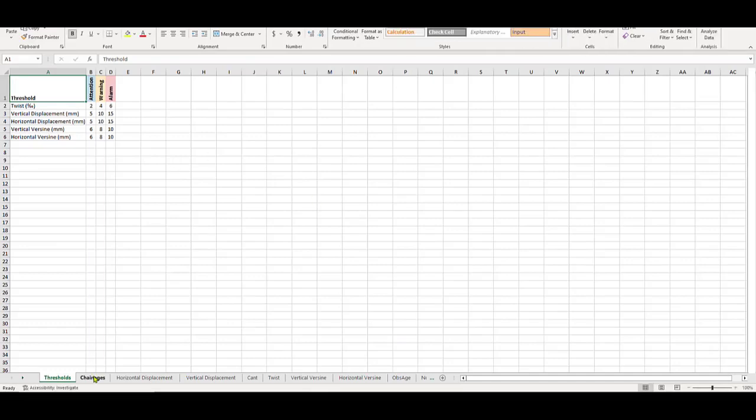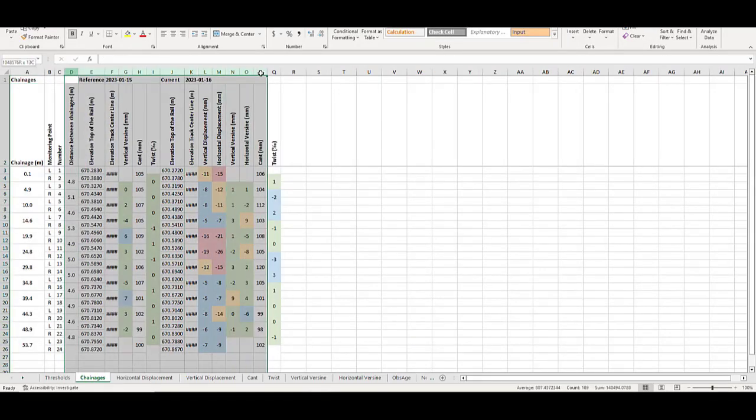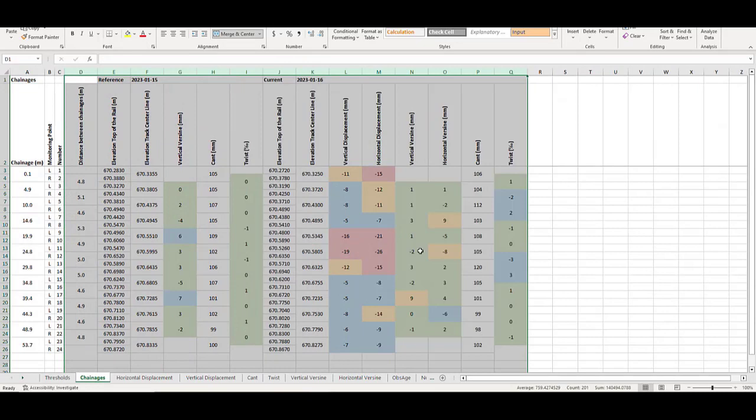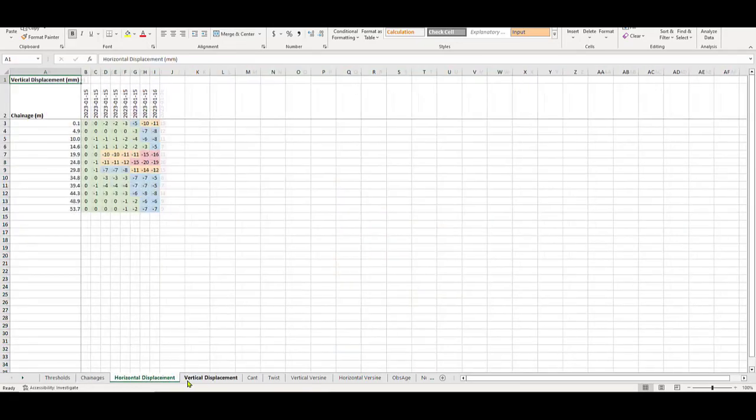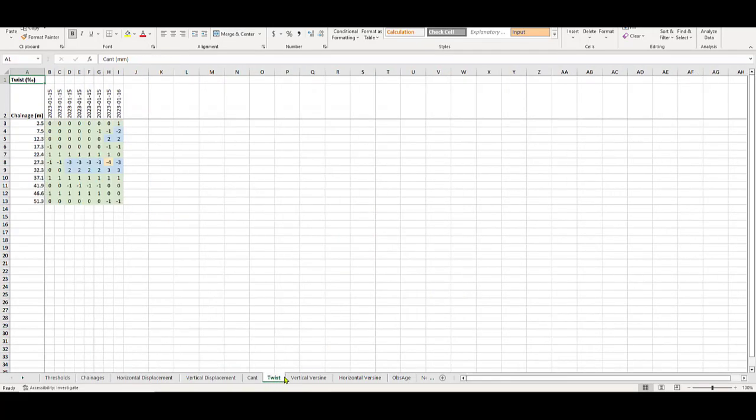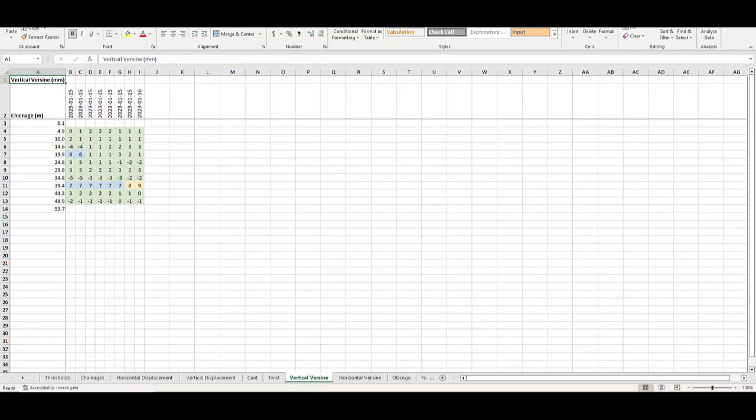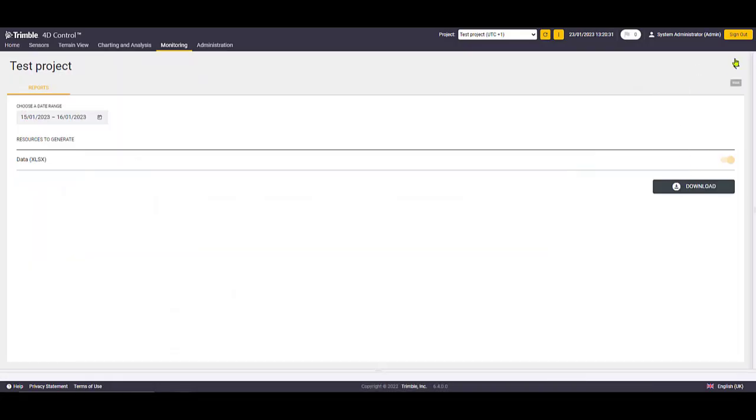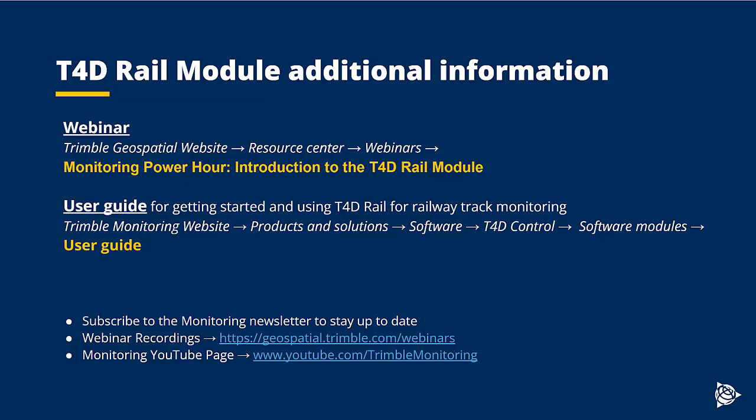If the rail monitoring section is disabled and settings or parameters are changed, a new measurement must be created and uploaded for the change to take effect. This video and data is meant for getting the first experience using T4D Rail. For more information, check the Monitoring Power Hour webinar and T4D Rail user guide.